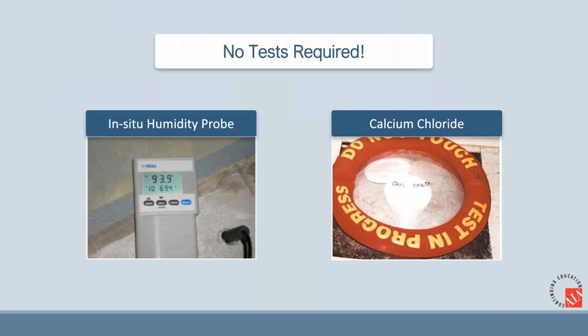Also, if you do the job right the first time, if you prevent everything from coming along, you should not need to do any other moisture testing. However, the industry does require or ask that moisture testing be done before flooring is installed. It's important that you do both tests. A lot of people out in the world today say, oh, I only need to use a humidity probe. I disagree. I think you need to make sure both tests are done if you don't have a system in place that guarantees protection. I can go over more detail on testing and the differences in the Q&A time.